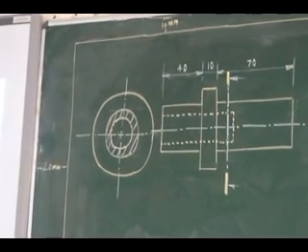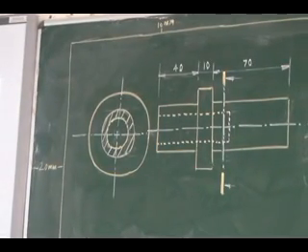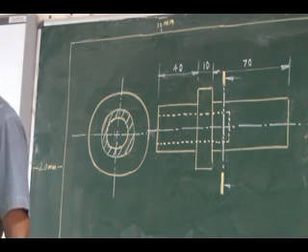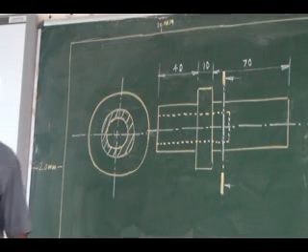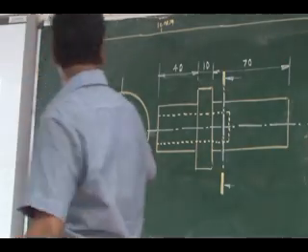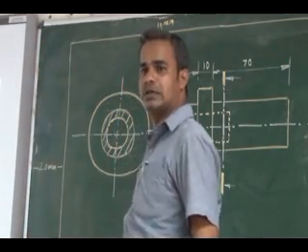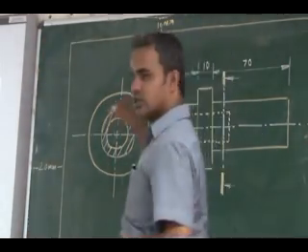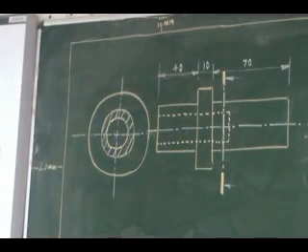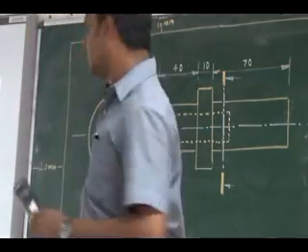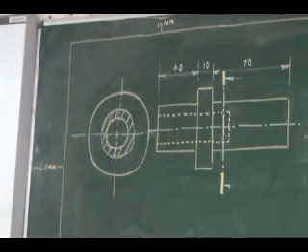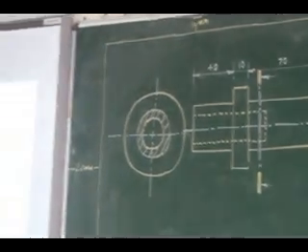So this is hatching. Hatching line is what kind of line? It's a thin one. A continuous thin line, and it should be drawn with a 2H pencil. So the section portion is shown here. The sectioning of solids we are going to see in a separate chapter. This is about lines.